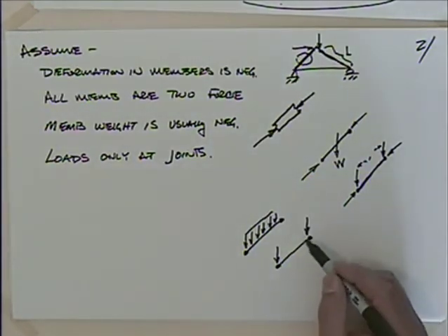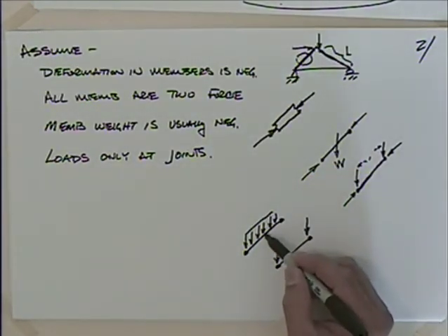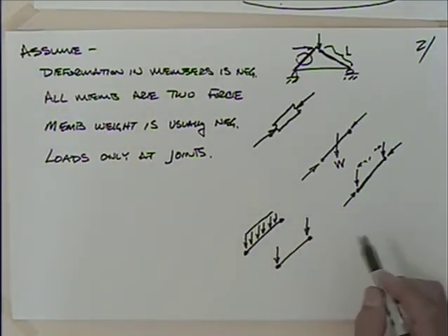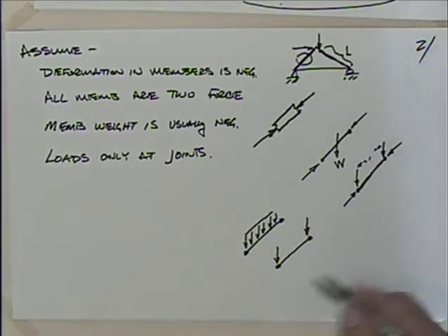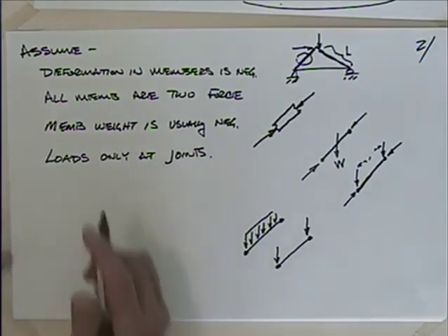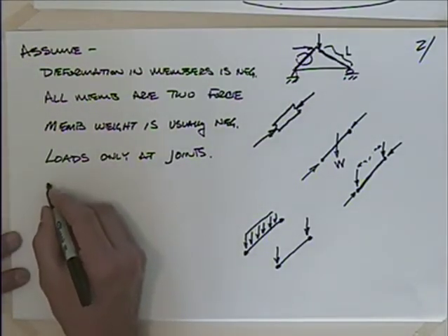There's secondary moments that are involved when you do this, and you go to an advanced class and you'll talk about it. Usually they're not that big a deal, actually. The primary moments that we're going to be talking about, or the primary forces, stresses, are the biggest. And we're going to model all joints as a pin.